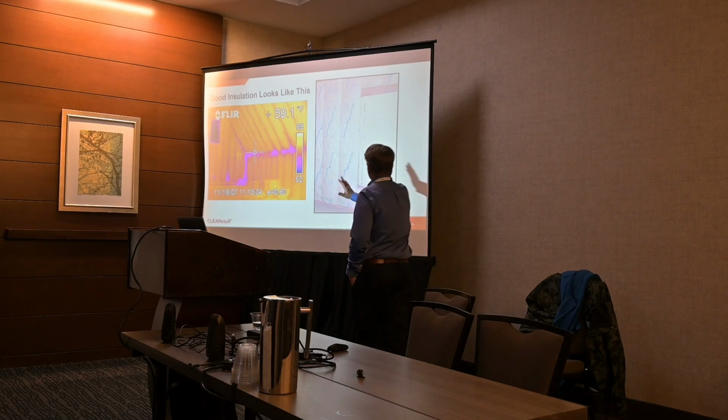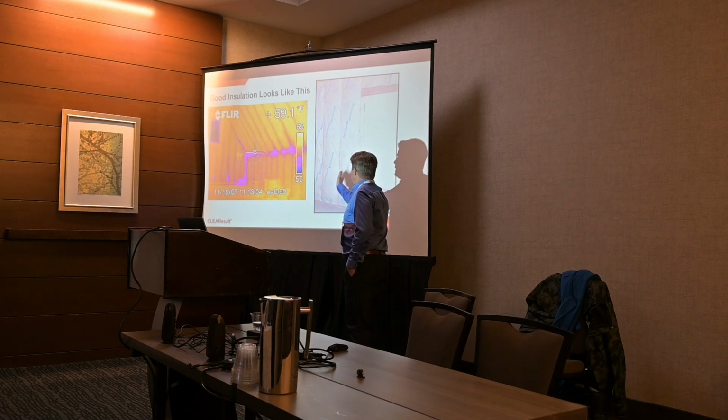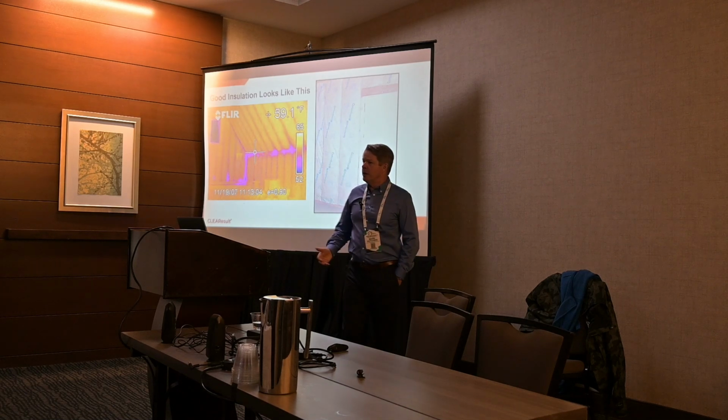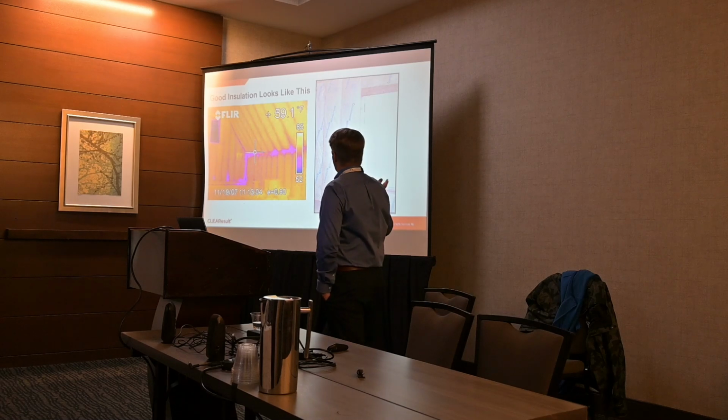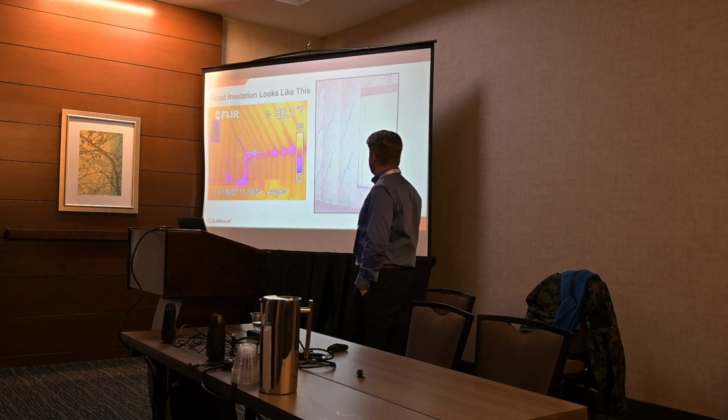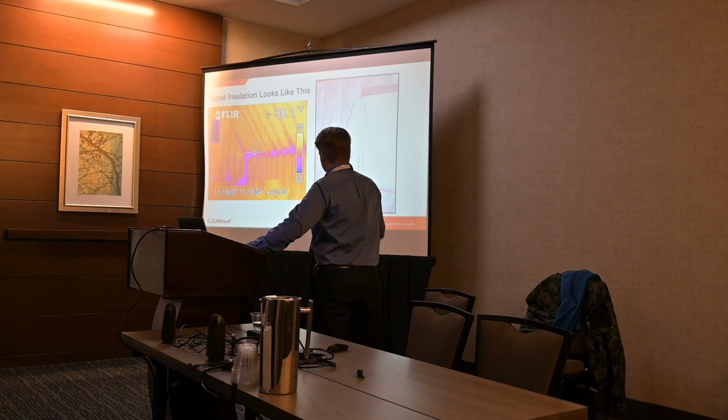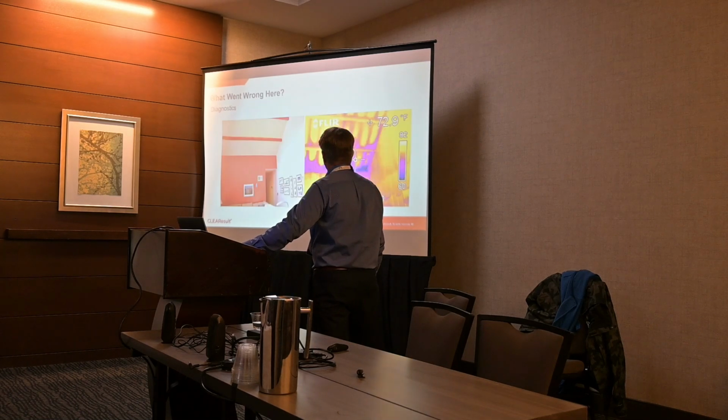A lot of times you'll see they'll side staple this, they'll push it in and side staple it. When you do that, you ensure compression on at least 2.5%. It should never be side stapled, always pulled over and face stapled. But you see no compression, no gaps, face stapled. That's a really nice installation.